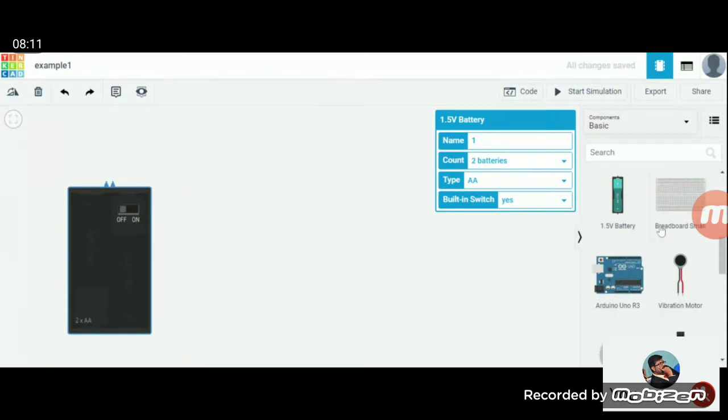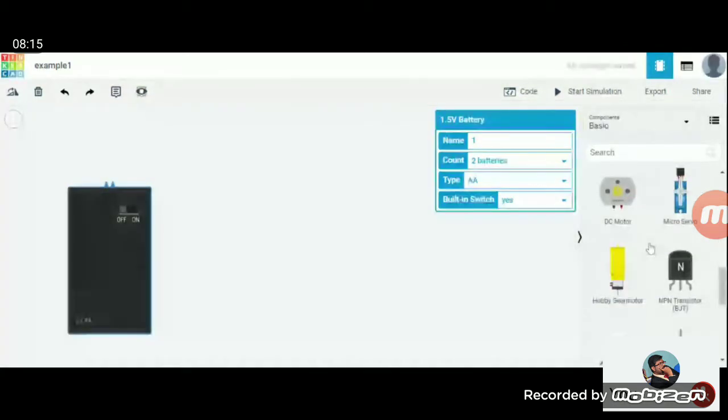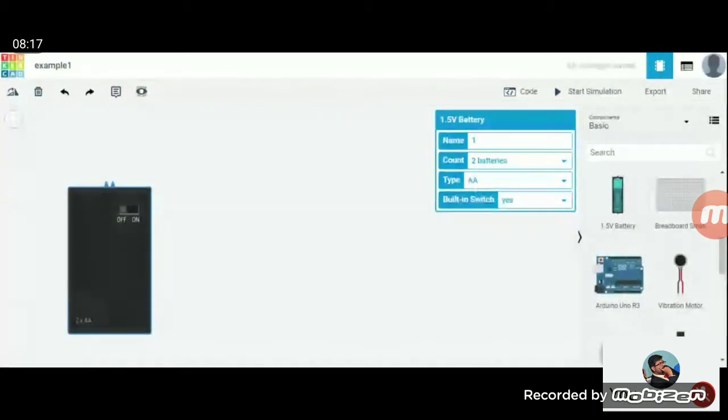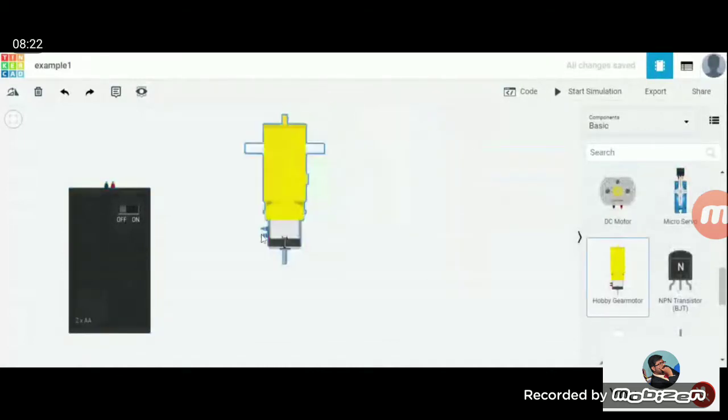Next, we will go with a simple LED connection, LED connection and motor connection. So let's see with a motor. This is a normal DC or toy motor which usually runs at lower speeds. While connecting, you have to be a little careful. What I mean is you need to find out the terminals correctly.